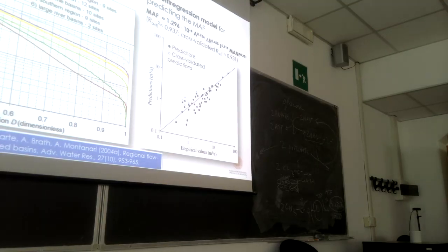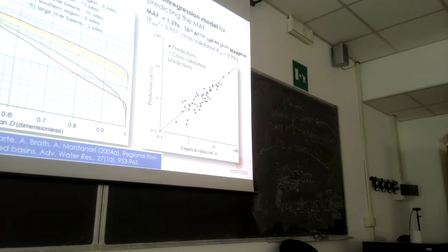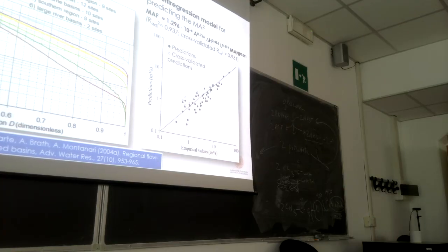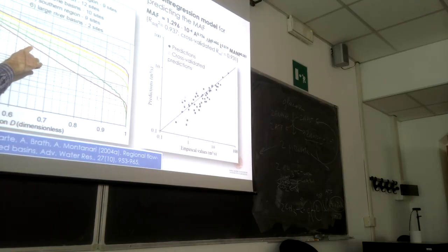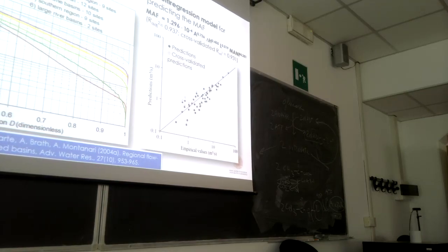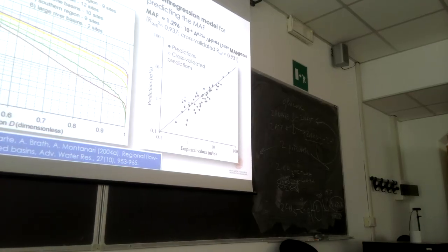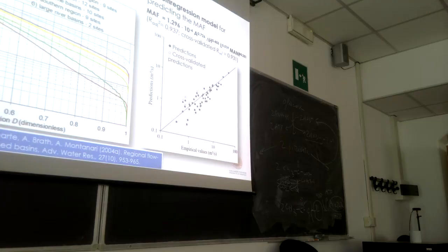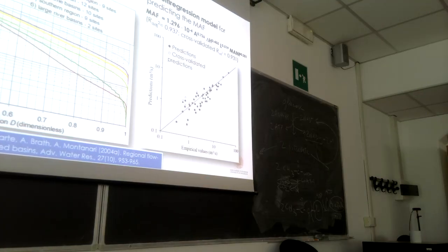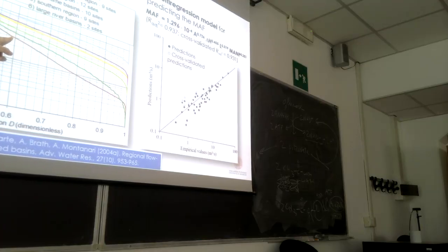So, your target site without observation is here. You pick the brown curve. Your catchment without observation belongs to this large system of karst catchments. You pick the blue curve. Your catchment belongs to the coastal, smaller and low elevation catchments. So it's a river cross-section here with a catchment that is coastal and low elevation. You pick the green curve.